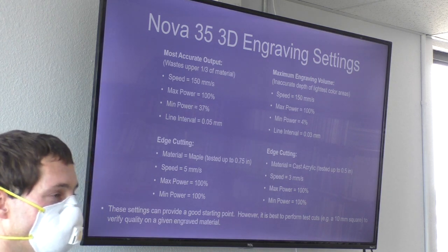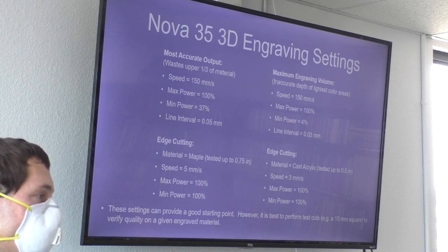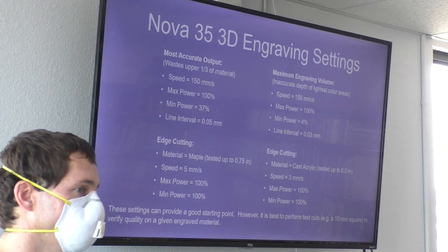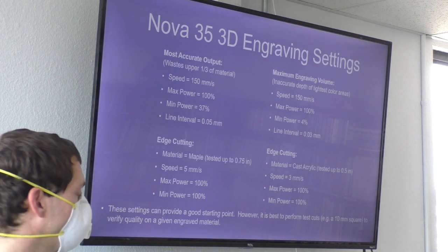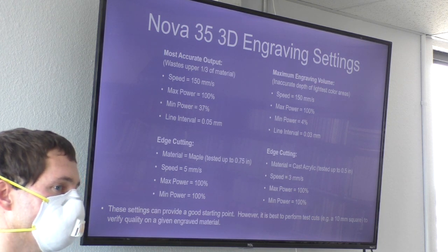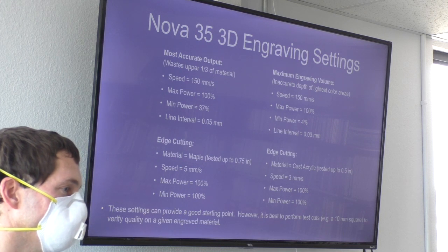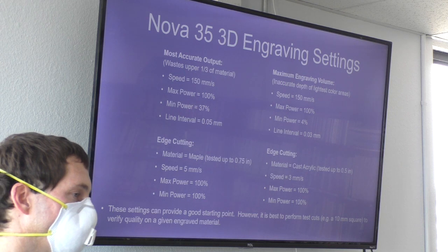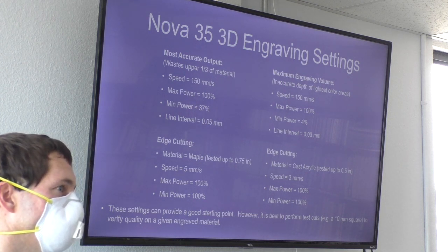So what about the idea, because I see in all of your slides here, and you've got experience, and Travis and others are more experienced than me. I'm still learning my lasers, and using this laser, I keep hearing from the people at Laguna and others that they don't want me to go to 100% power except on rare circumstances. They want me to run it at the lowest power with the fastest setting I can, to preserve tube life, they've said, among other things.